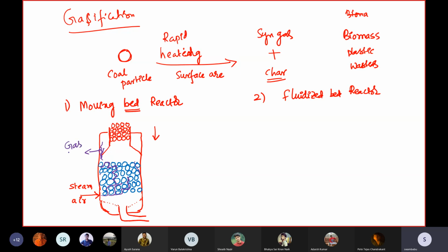This gas will contain syngas, but it will also contain CO, H2 and CO2, and we will also have H2S, because some sulfur components are there, and we will also have mercaptans and many other impurities. But predominantly CO and H2. If you see the concentration, it will be almost 80 to 85% syngas. Not above that, I think, but it depends on the coal.